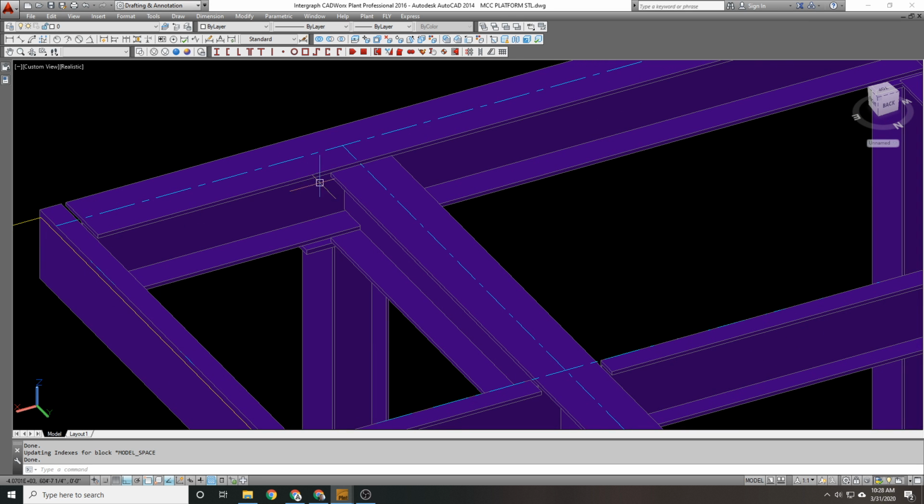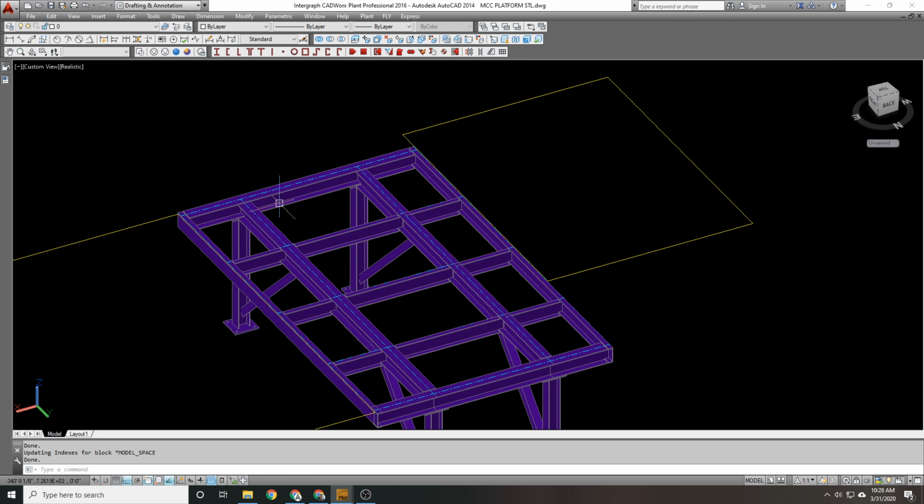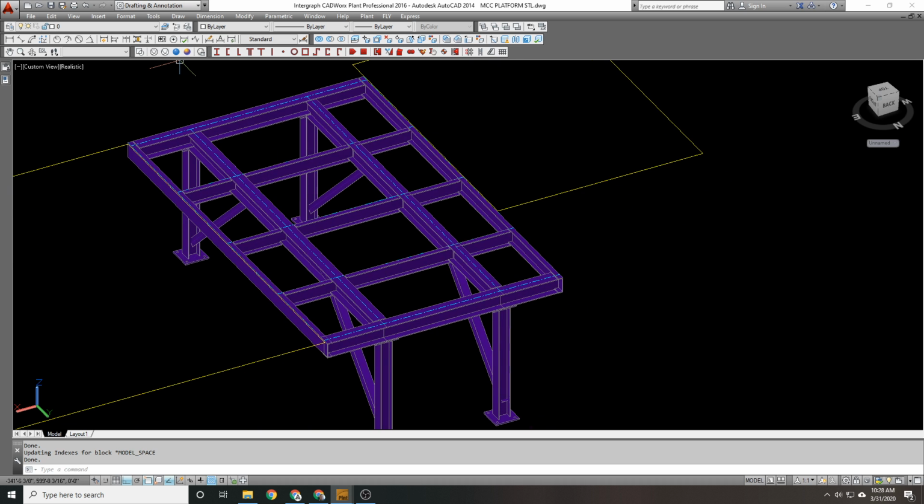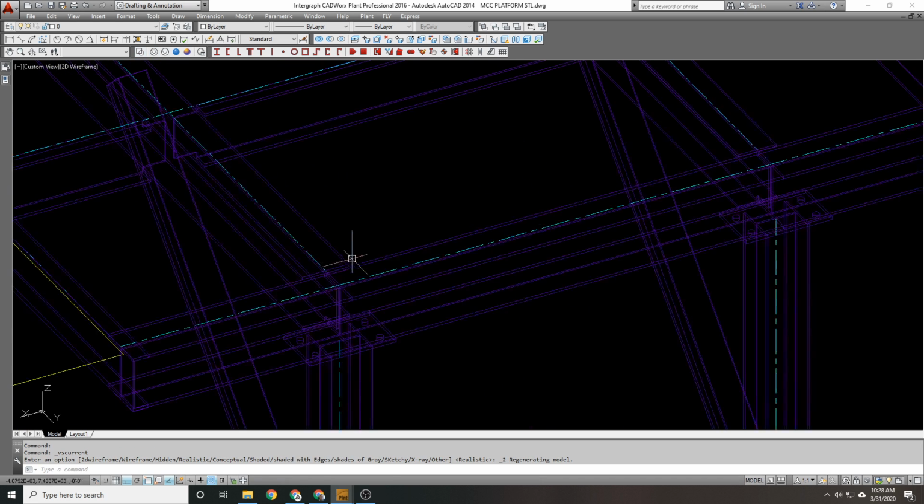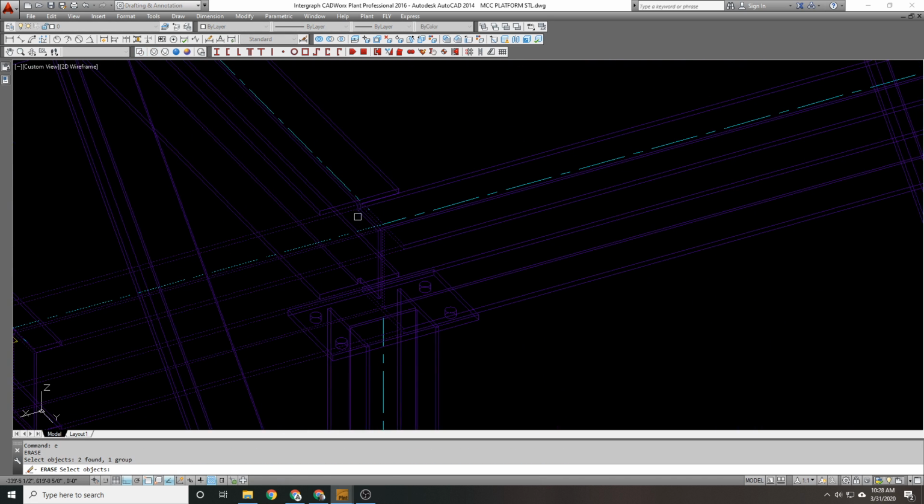Had this come to like here and stopped, and this was a through member, then absolutely you're going to need bracing to handle that cantilever because it's pivoting right here. But with this going all the way, it can handle a cantilever of whatever we have here, like 2'4", 2'5", something like that. So I'm going to come back here.